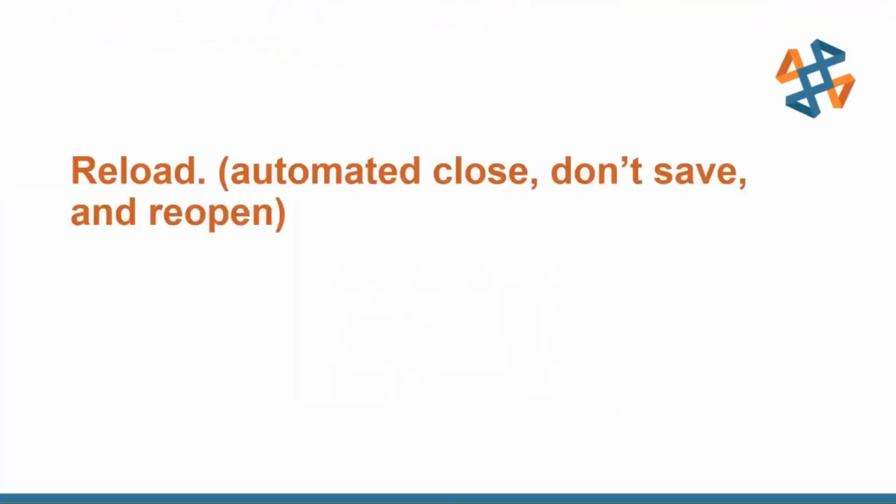Here's one that really gets overlooked. Again, I'm an older SOLIDWORKS user. I find myself not using the most efficient way every day. And I fall into this trap as well. A quick way to close a file, not save it, but reopen it, and that is the Reload command under the File pull-down menu.